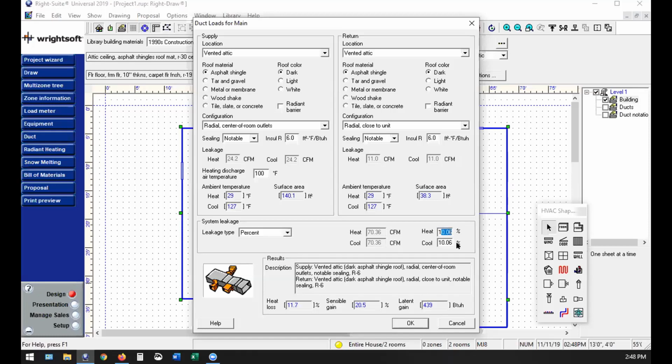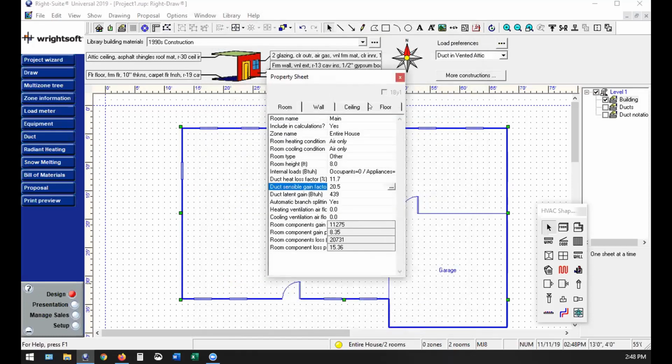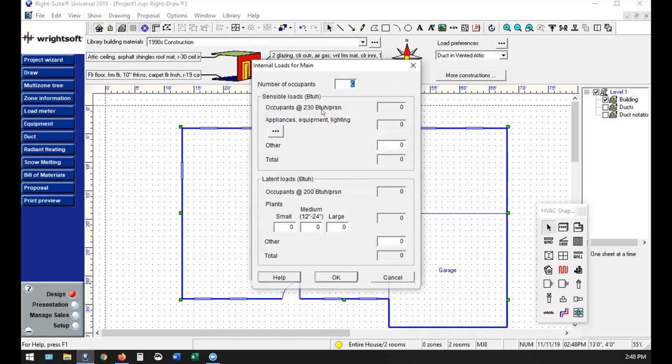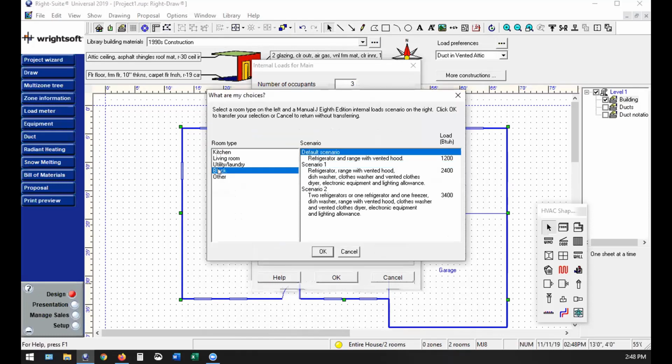So if you do a duct leakage test, you can plug in those numbers in your load and make them that much more accurate, because it's going to have an effect. And the 2 biggest places where there's guesswork are duct leakage and infiltration, in my estimation. So I would also want to put in some people and appliances for the load. That's a part of the process, right? So we put in those people and appliances. Oh, wrong thing. It's not a kitchen. It's a block load.